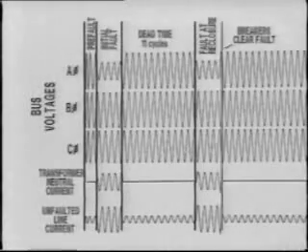So the breakers immediately tripped out again and locked out. If this problem repeats itself over a period of time, we may conclude that 11 cycles of dead time is not enough to allow the temporary fault to deionize and dissipate. In this case, the dead time would be increased by changing the time delay at the breaker.